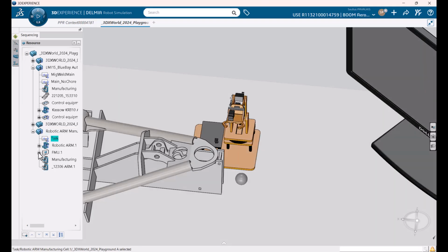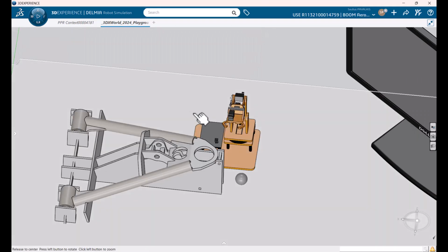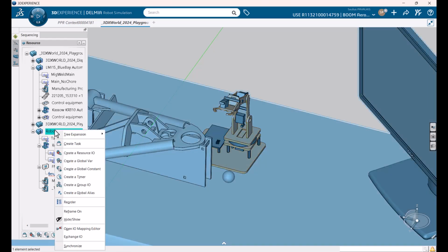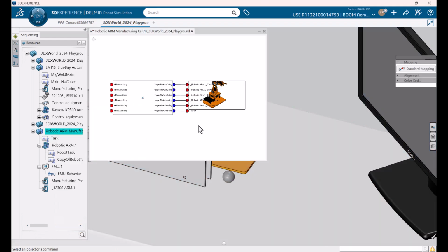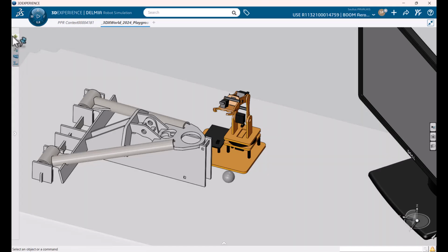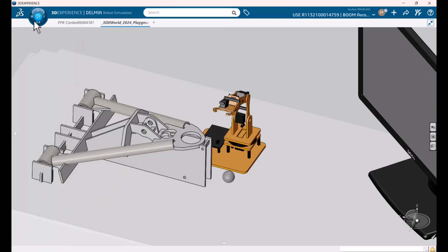You see here, it has its own program. Here we see this robot has its own program. You see, like it executes by itself, and will trigger that program. But also, it can listen to the external commands. And how it listens, you see here is FMU interface. FMU added one of those we just generated, and it's mapped here. Let's check. Here we have, you see this is mapped here to this robot. Okay, now I can select this one, task to execute, and I can run this.